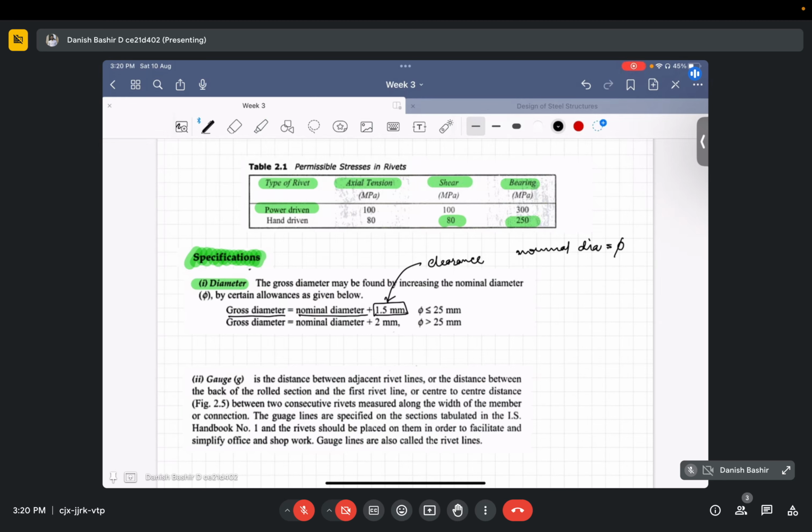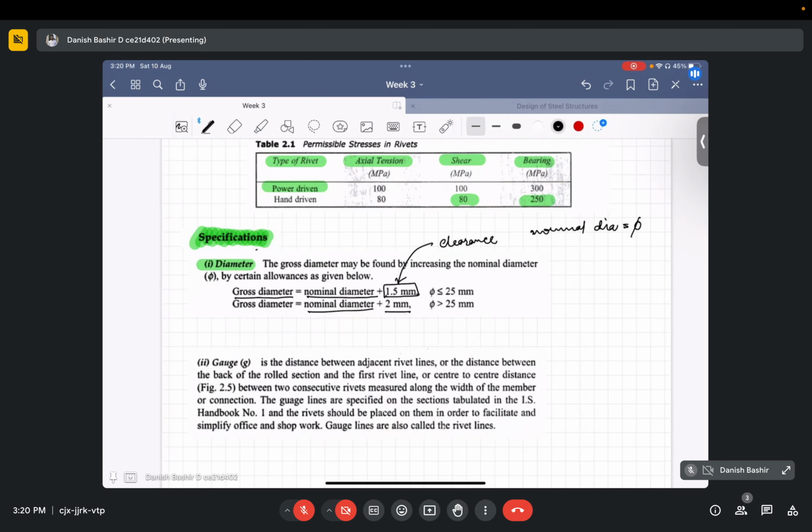It is for the diameter of the rivet less than or equal to 25 mm, and for greater than 25 mm, gross diameter is equal to nominal diameter plus 2 mm. Okay, I hope this point is clear to you. Then there is one more concept, which is gauge.